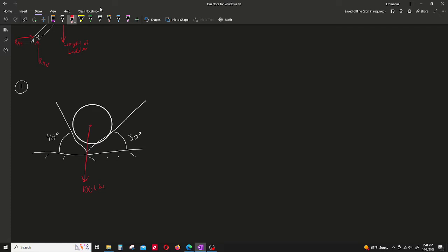All right. So we do know, since this is leaning up against these two surfaces there, we have some additional forces. I'm going to redraw my free body diagram out here like this. We have a force acting on the body there, a force acting on the body there, and a downward weight force happening there. This is FB. This is FA, or you can call it F1, F2. It really doesn't matter what you call it, as long as you keep them consistent.